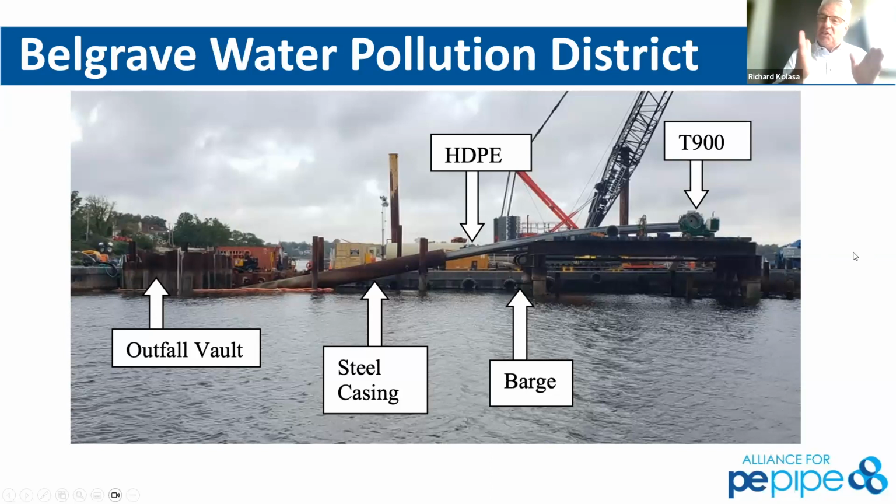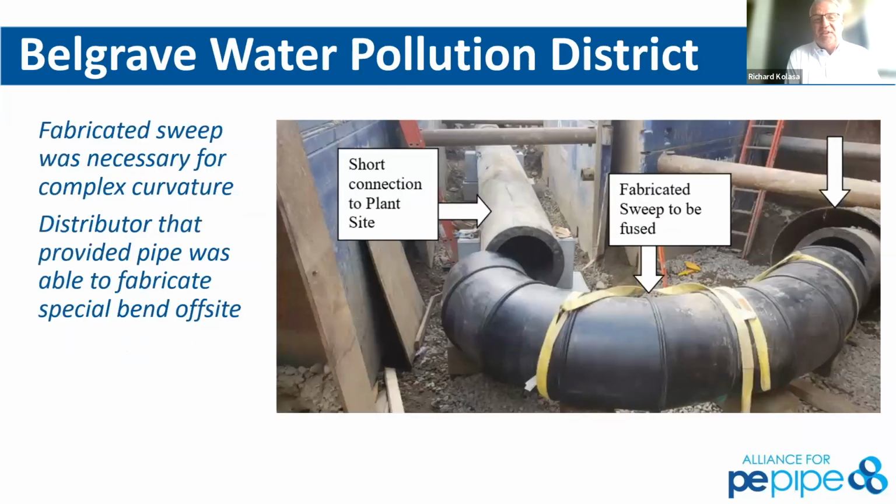So what we did, instead of chopping a section out of the lengths of pipe, we actually sent them 3-foot sections of the diameter of the pipe and the DR that we were using, so they could test it in the fusion equipment so it wouldn't take away from any of those lengths. And then we would destroy those and produce the samples for tensile pulling and bending, to check those fusions and fusion conditions. And they all passed. It was a great success.